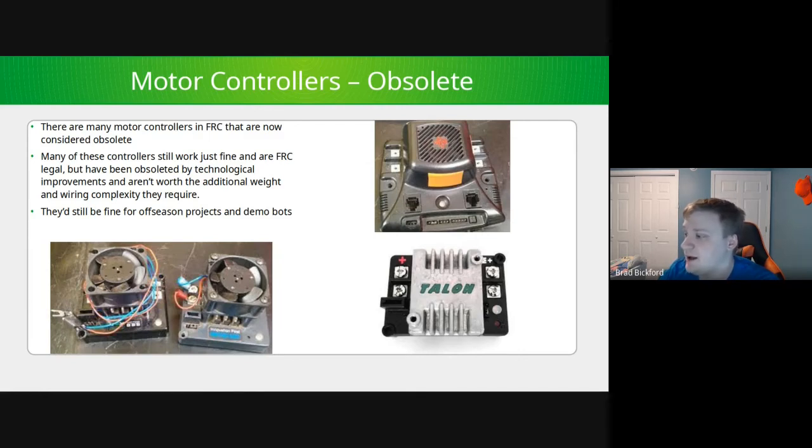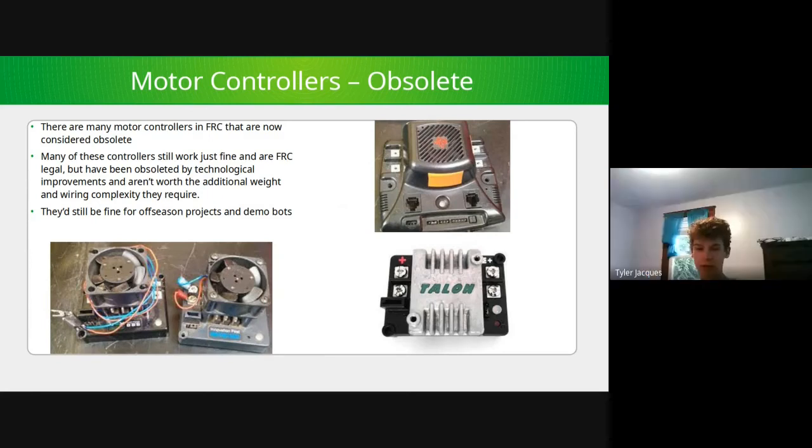Cross the Road Electronics has their own robot controller, like beyond the Robo Rio. It's called the Hero. And I assume that the SPI functionality can be used in some way with that. But I don't believe that it's FIRST legal to use SPI to control a motor controller, even though it is available. SPI wouldn't be very practical for motor controllers anyways.